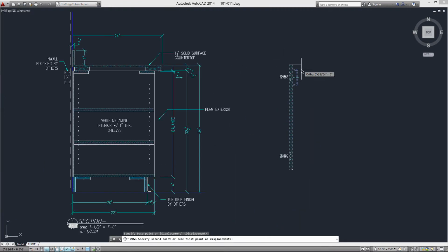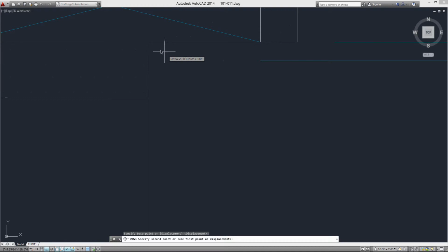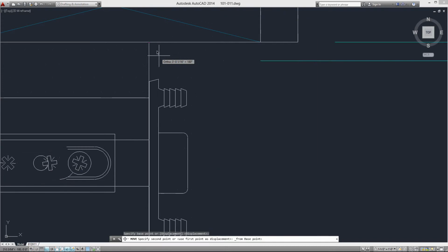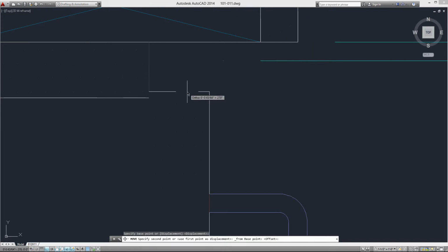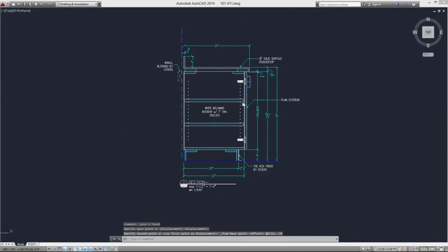All right. So now I'm going to grab the entire door assembly. Start move command. Now I'm going to position this relative to the top of the face of the cabinet. And I'm allowing 3/16 of an inch for the hinge gap and 1/4 of an inch for the top reveal. All right, so I'm going to choose the top of the face, shift right click F for from. I'm going to choose this point. I'm going to do @3/16,-0.25. And there you have it. There's the door in its proper position.